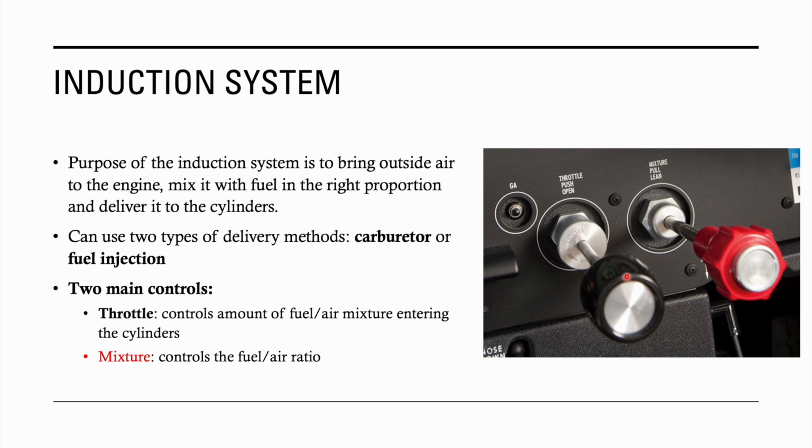You can think about it like a gas pedal in the car. So if you push this rod forward, it's like putting your foot down on the gas pedal. So you're giving gas. And if you pull that rod out, it's like taking your foot off the gas. So the throttle is controlling how much fuel or mixture you're letting into the cylinder.